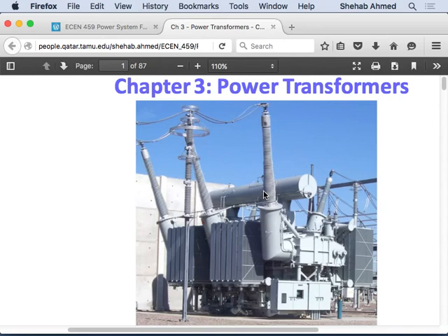So one way to do it is just keep it without running the pumps. And then in that case, the heat from the windings will heat the oil, it will rise, move through the radiator, cool down, come back to the system, and you have a closed loop, right? And if you force this closed loop, then you're doing a better job of cooling, obviously, right? You're going to be forcing the oil to move around quicker, and you'll be able to cool the transformer better.